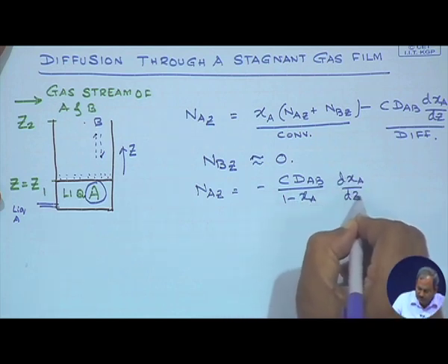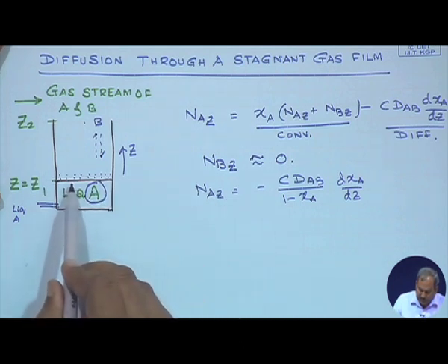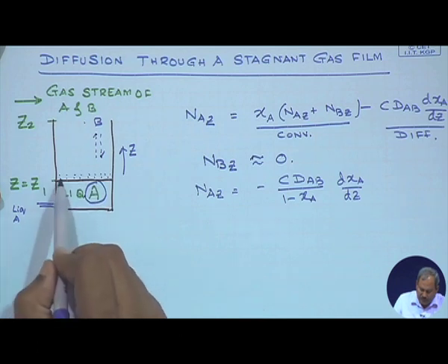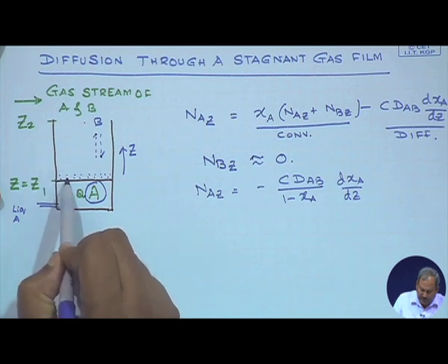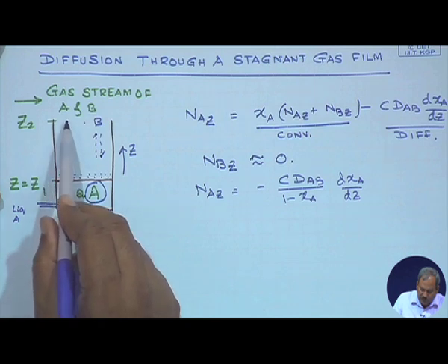Just a quick observation here is, if it is mentioned that the liquid A is not highly volatile, let us say it is just water, and the water molecules, when they change phase, the number density of water molecules would not be large, and therefore, the entire motion of the water molecules towards the mouth of the tube will be governed by diffusion, by only diffusion.